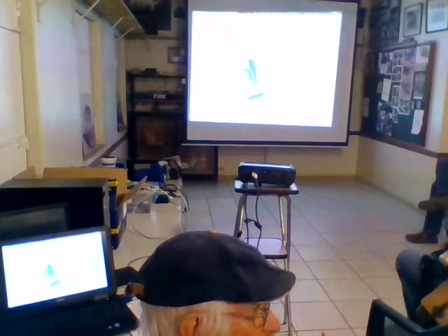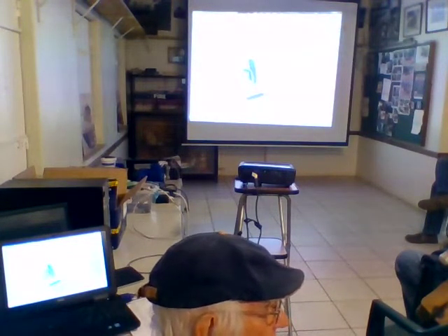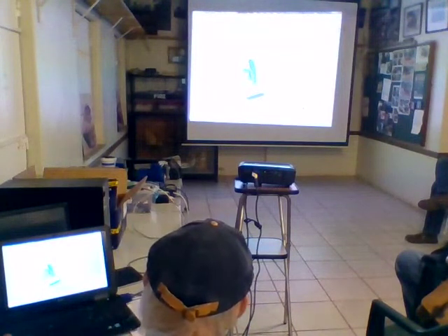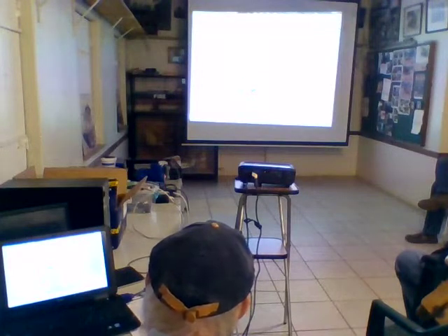Then you have to have a specific built-in spindle, and you can't change the spindle easily. Ideally would be to box it up. So I've increased the stiffnesses and the thicknesses here on this vertical axis to increase its torsional stiffness, and closed it up at the bottom and the top and so on. And I'm happy now with that.